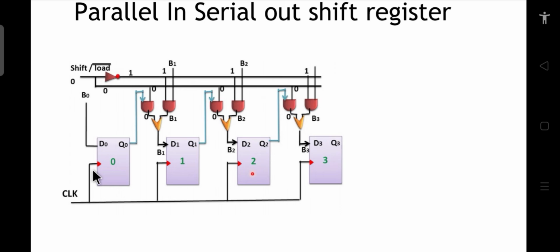When each clock pulse appears, on the appearance of the first edge of the clock pulse, the output of the D0 flip flop will be 1. On the appearance of the second edge of the clock, this will become active, and so on and so forth.